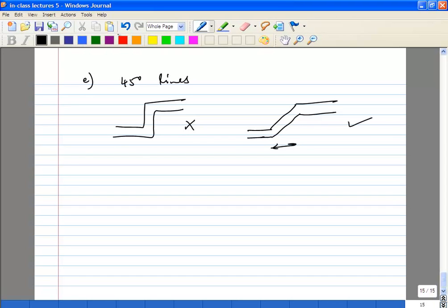Because what happens is, typically when you are looking at high frequency currents, you tend to have current crowding. I think we looked at this when we saw the inductors, right? You'll end up having current crowding right at the turns, and so your current density will increase. There are a lot of effects. There is something called electromigration, where if your current density increases at a particular point, your metal starts to erode. So you might have issues like that. So 45-degree turns are much better.